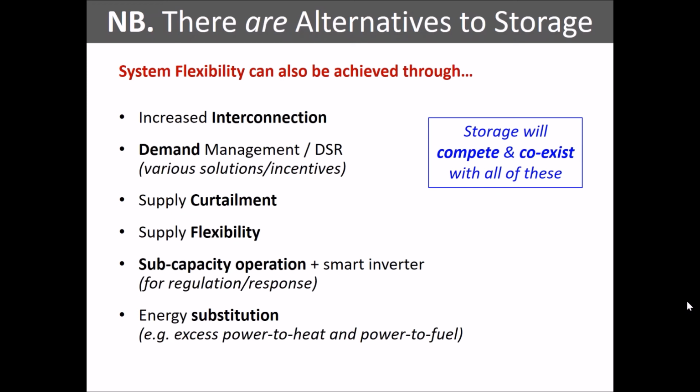Let's have a look. Reduction in grid capacity has only really been mentioned, not entirely explained yet. Is this from its ability to provide reactive power support or reduction in peak transfer capacity? Okay, yeah. Obviously, when we're talking about grid capacity, it depends where in the grid we're talking about. If we take something like large-scale wind power plants, they tend to be built in places away from centres of demand, because it tends to be windy places where people don't necessarily want to live. So you can end up with quite a lot of capacity supply built in areas of the grid where the grid, if you like, is inherently weak. It's not been built for great big power plants. It's in more remote regions.